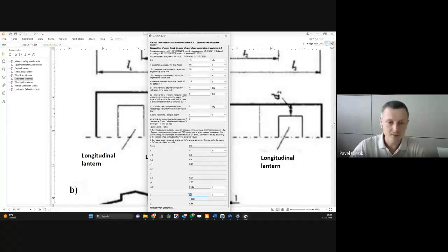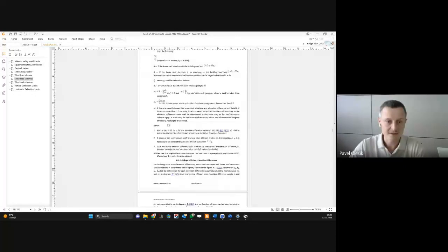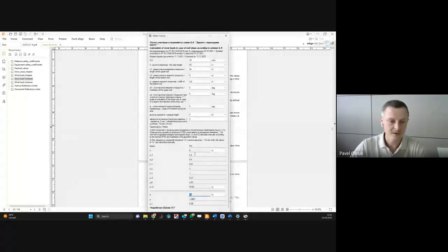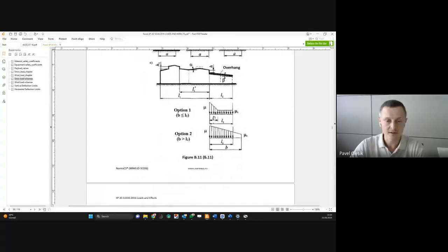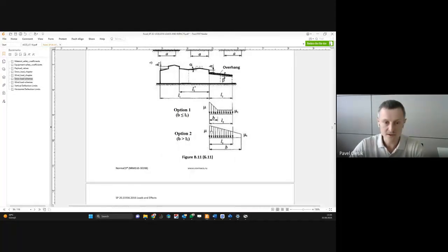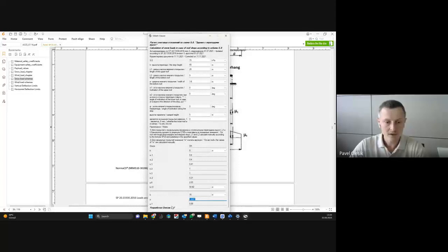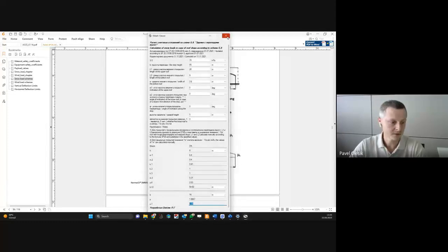And as a result, first of all, you can check everything according to these formulas. They are different formulas. You can check my calculation. And also you can get the result for our snow pocket. It's written here. Our length B of the snow pocket will be 16 meters. Mu, this coefficient, will be 1, and mu1 will be 0.95. So it's a very easy program, and you can use it. I will share it with you as well.